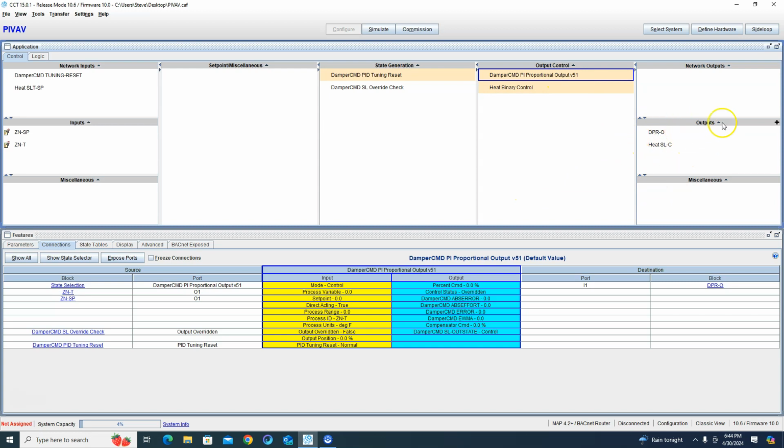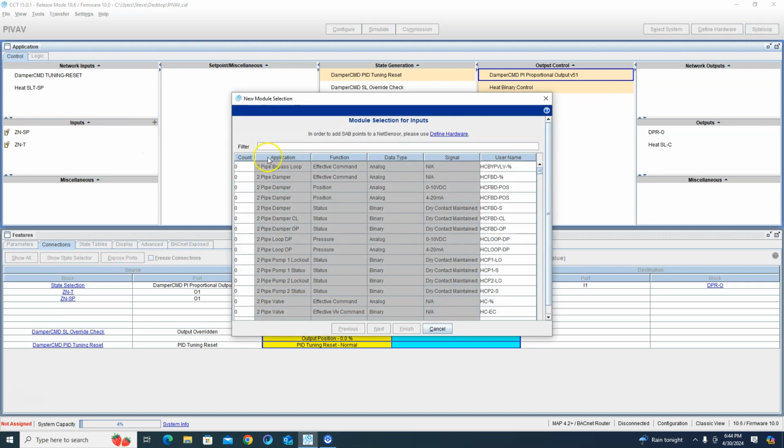Same thing if you had a fan power box, we just tie a fan command into this heating program and the fan would come on at the same time. Okay. But now say you're hooked to a rooftop unit that actually outputs heat. You don't want your damper acting in cooling fashion when it's blowing hot air, right? So no problem. We can do one or two things. We can get a signal from the unit itself and reverse the action of the PID right here, direct acting to false. Or we can look at a discharge air temp,